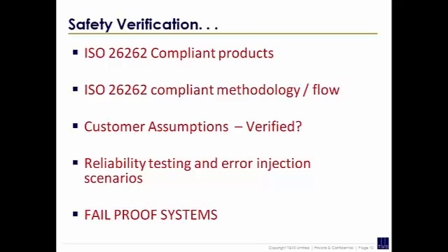Then we have another thing called random error injection. In random error injection, you randomly flip some bit in the system, and we have random generators where some bit will be randomly picked, and now the test case goes on. Will it be really caught down the line? This is random injection. And then there is something called error edge injection, basically for memories. Initially the built-in self-tests are run, and are we able to catch if there are any issues and things like that. So there are different classifications within that.